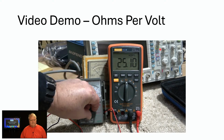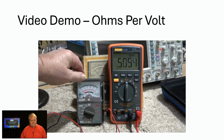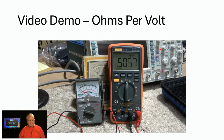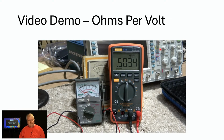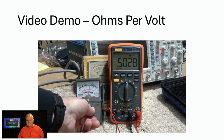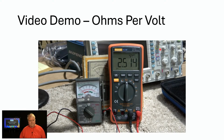If we go to the 50 volt scale on the little snap-it meter, 50 times 10,000 is 500,000, or 0.5 megohms, as indicated on the digital meter. And if we go up to the 250 volt scale, it's 2.5 megohms.